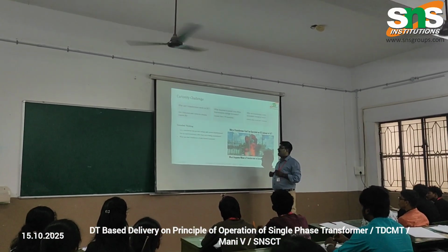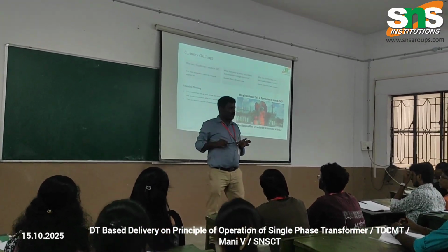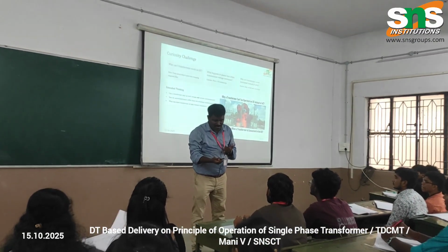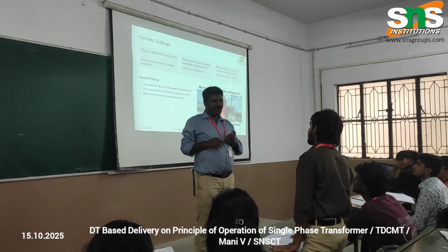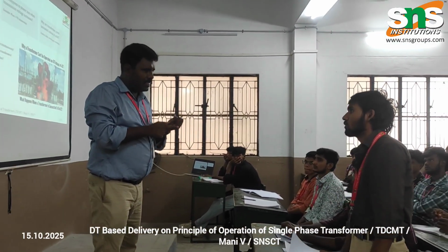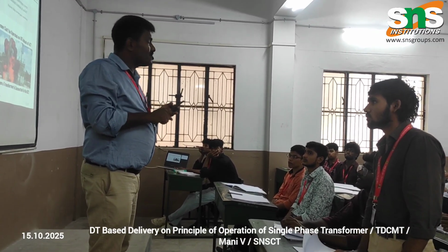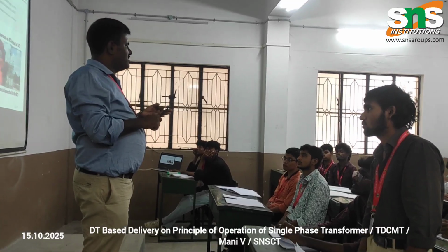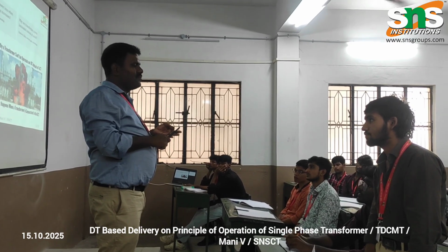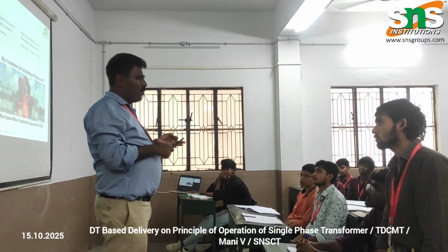Now, do you know why the transformer won't work on DC? Why won't the transformer work on DC? There is no frequency, so there is no change in flux. If there is no change in flux, it is nothing but stationary flux. If it is stationary flux, the EMF won't be induced. So the transformer won't work.